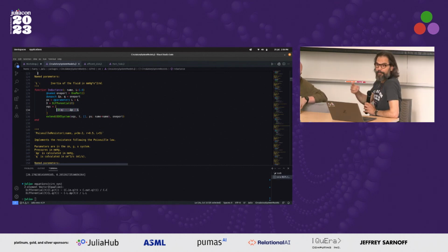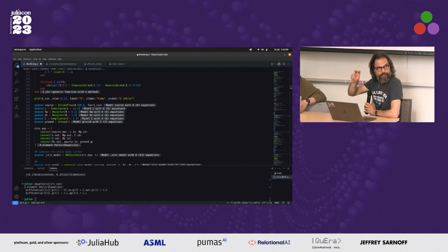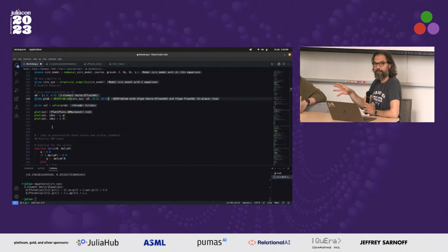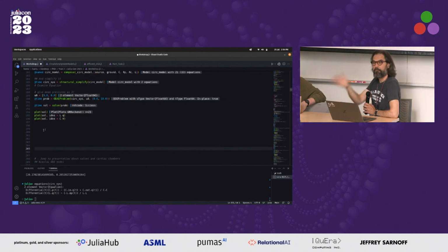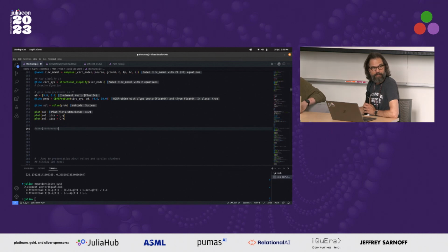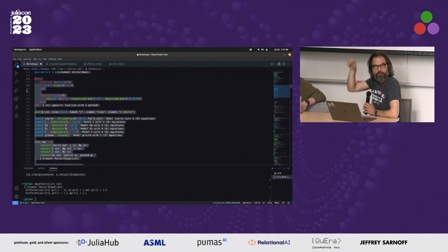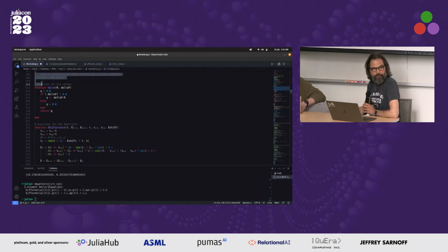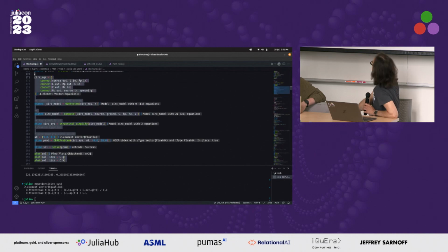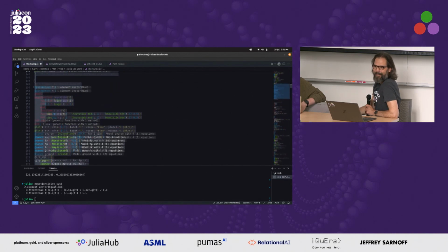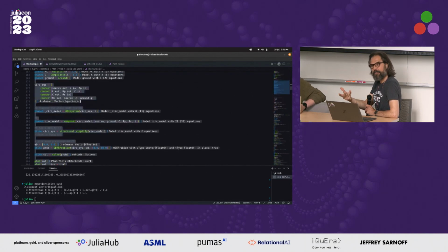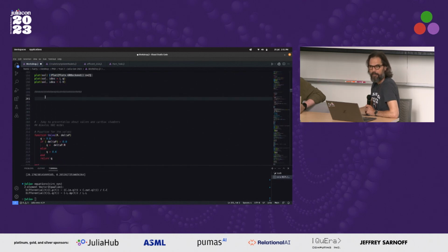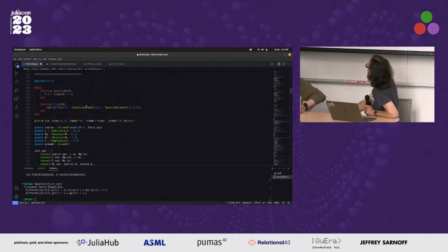If you define it as two parallel resistors, then I don't know what the system's going to do, but I would expect it to just take that out and have one resistor term in there with 1 over R1 plus 1 over R2 to the power of -1. So let's check that: replace the inertance with a resistor, and then it will optimize it and simplify the equations accordingly.